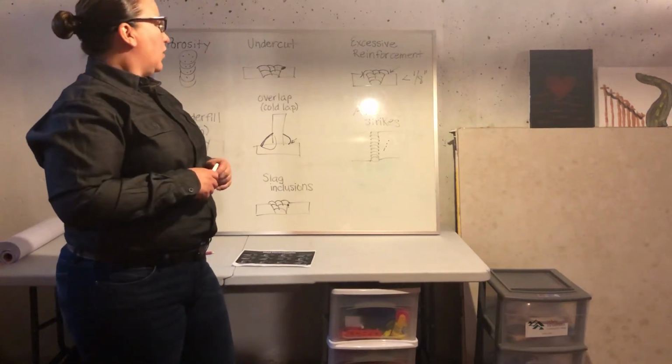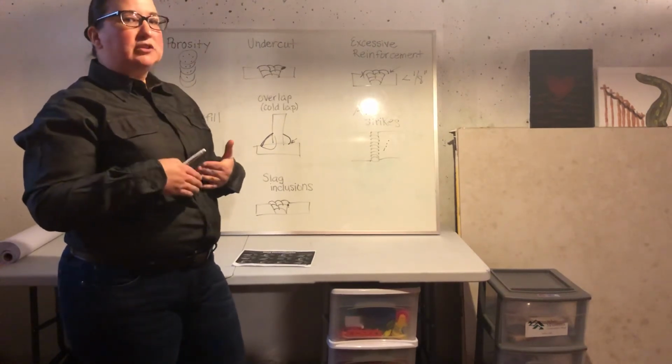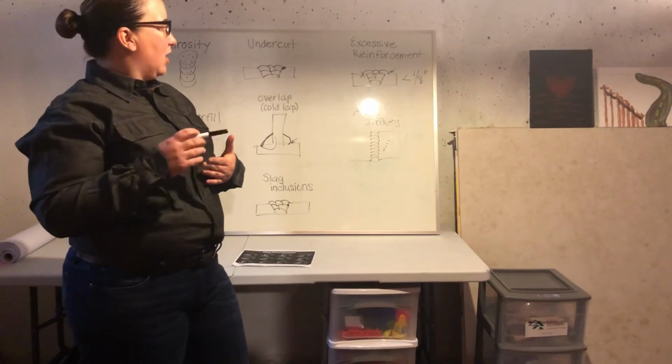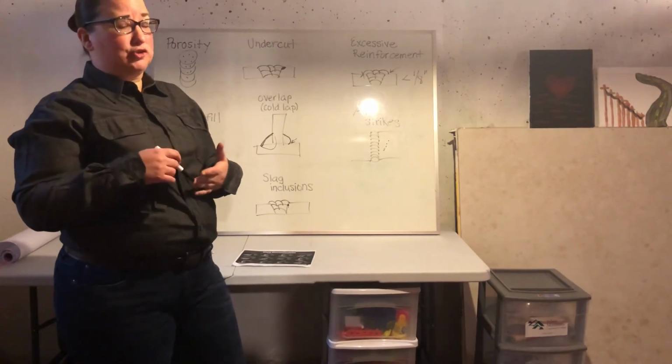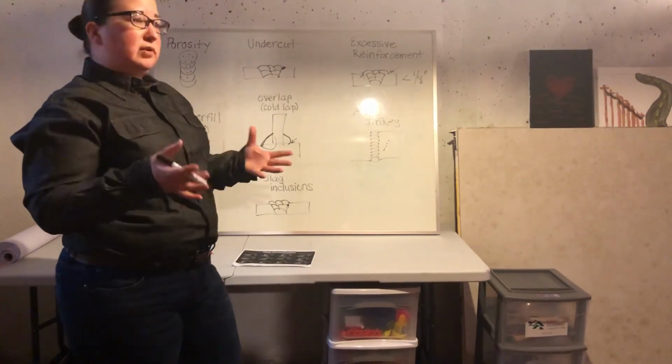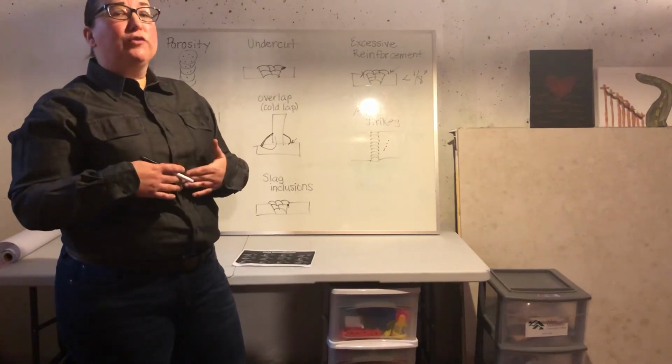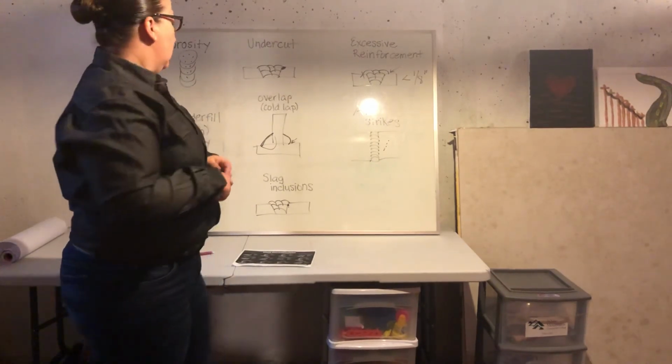So we really concentrate, especially on our restarts, making sure that we're starting that arc up inside our weld joint, so we can completely tie that back in and cover over that with our weld metal. Really, really important.